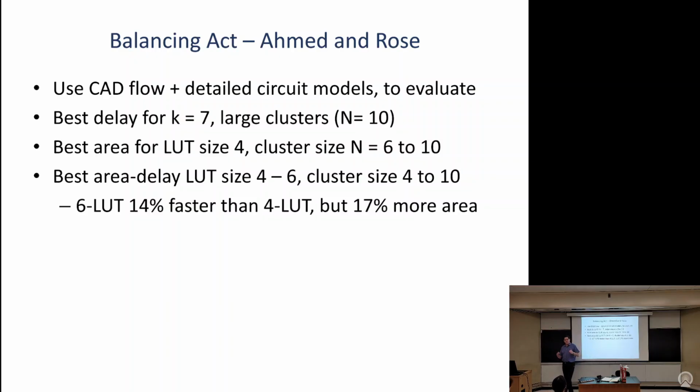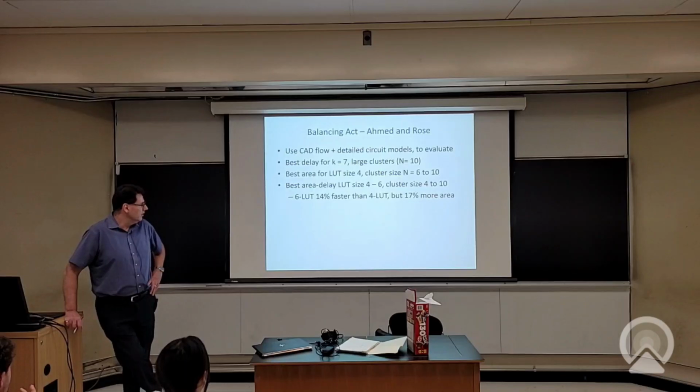Okay, so while the 6-LUT and 4-LUT best architectures are close here, they're close in different ways, in terms of what optimizes delay versus area. Yeah? Building off of Adam's question as to why Altera and Xilinx have gone to 6-LUTs and someone like Microchip might stick with 4-LUTs, could that reveal what their value proposition is trying to be for their customers?